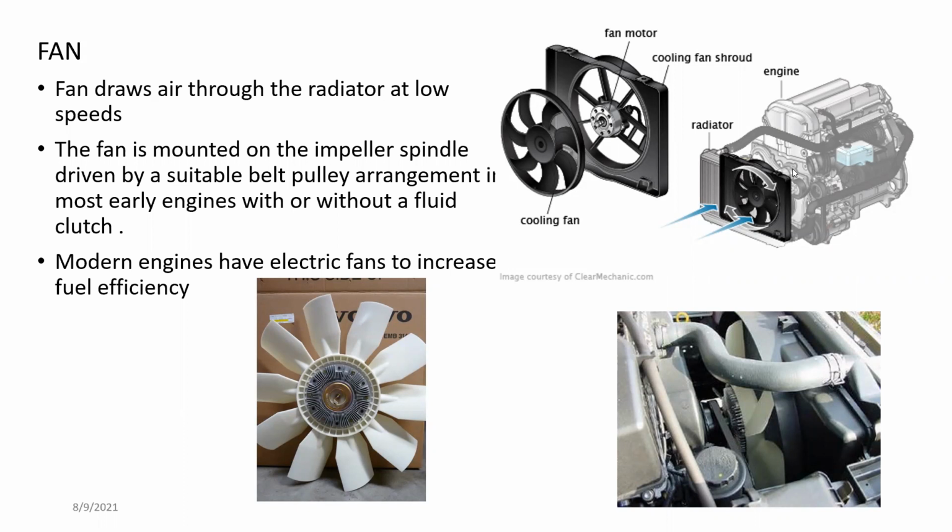Even with a transverse engine assembly, it's possible to use a mechanical coupling, but it's quite difficult to fit the belt. But there are some applications. One good example is the Peugeot 305 engines. They have a transverse engine layout, but the fan is still mechanically driven. They used a belt driven system, and the belt can turn 90 degrees with proper arrangements. So that's the purpose of the fan.